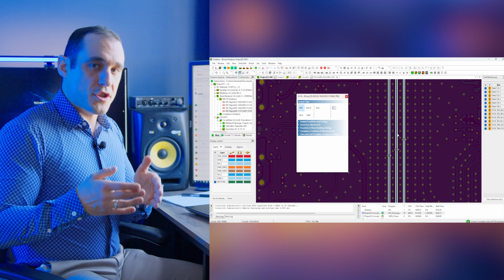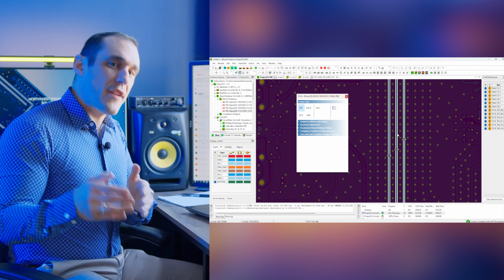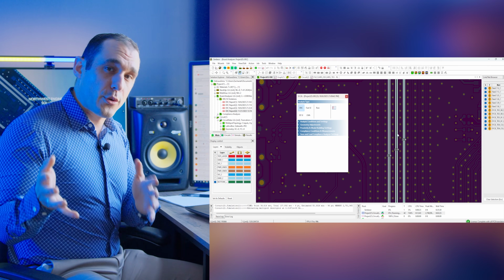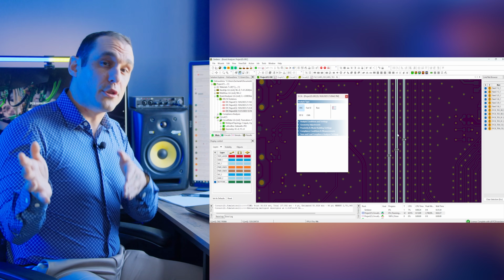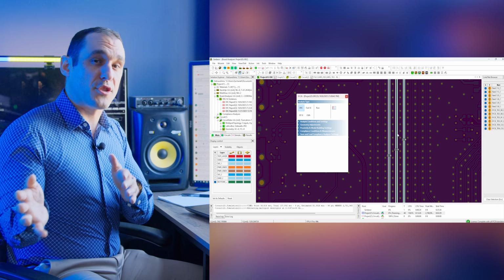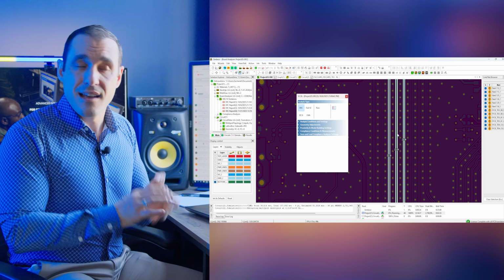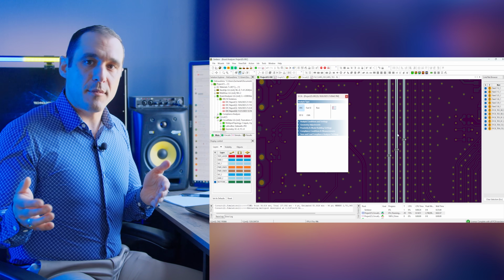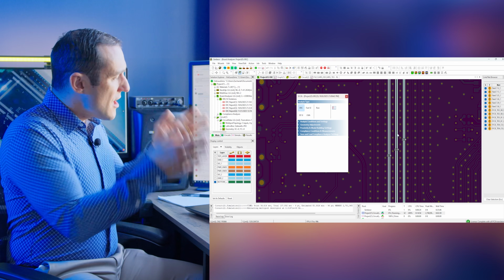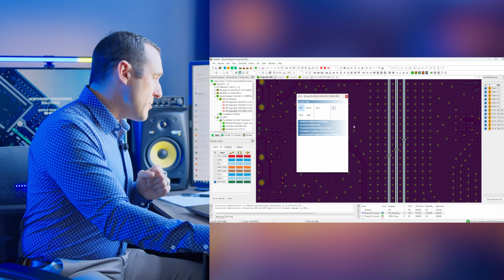All of those configuration settings are streamlined inside of Simbeor, so you can go through and very quickly build a full 3D simulation for this interconnect. And that interconnect could include vias on it. And that's another thing that's really powerful. Normally, if you have to do via simulations in 3D, again, you'd have to go into a tool like ANSYS or CST, and it's very time consuming to set up those simulations. Simbeor already has the tools built in to do that directly from your PCB layout.